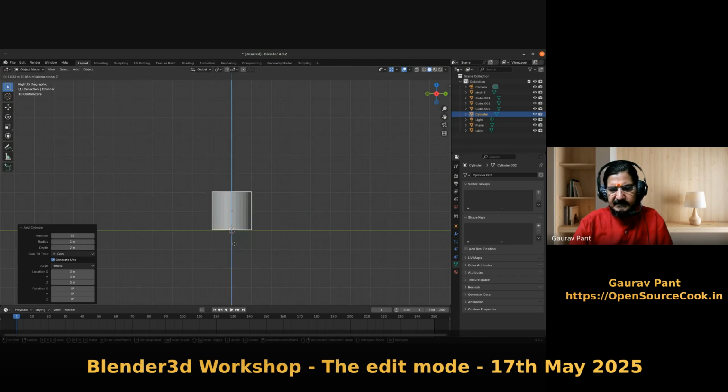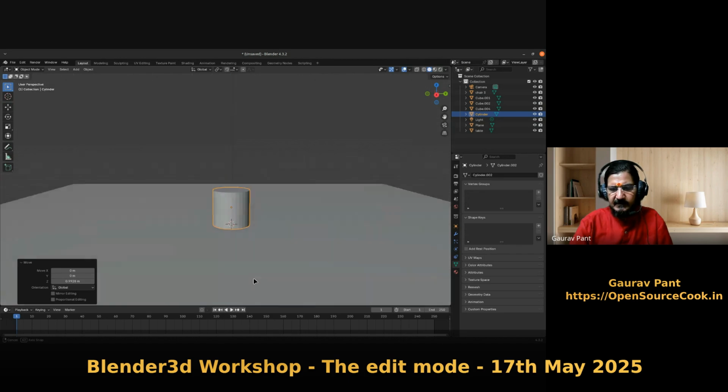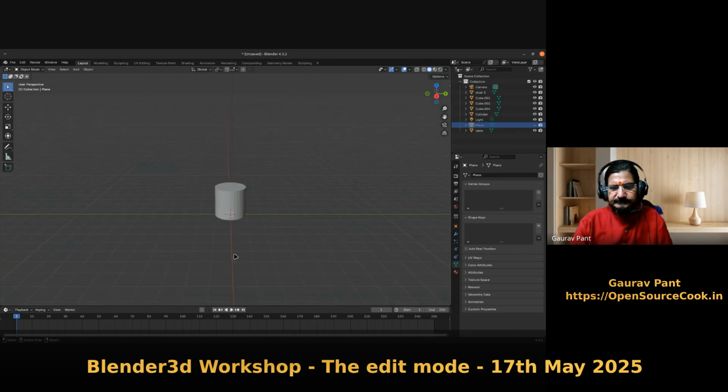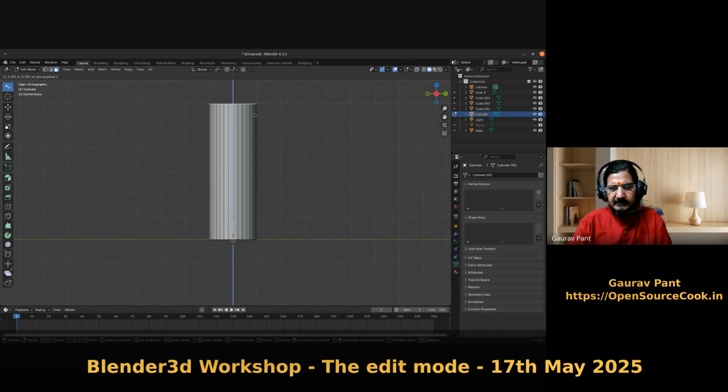Grab this on Z axis. Fine. And now let's get into the edit mode. Now what I'm going to do is I'm going to go into this view. I have selected the top face. Fine. And I'm just going to grab it and take it here.